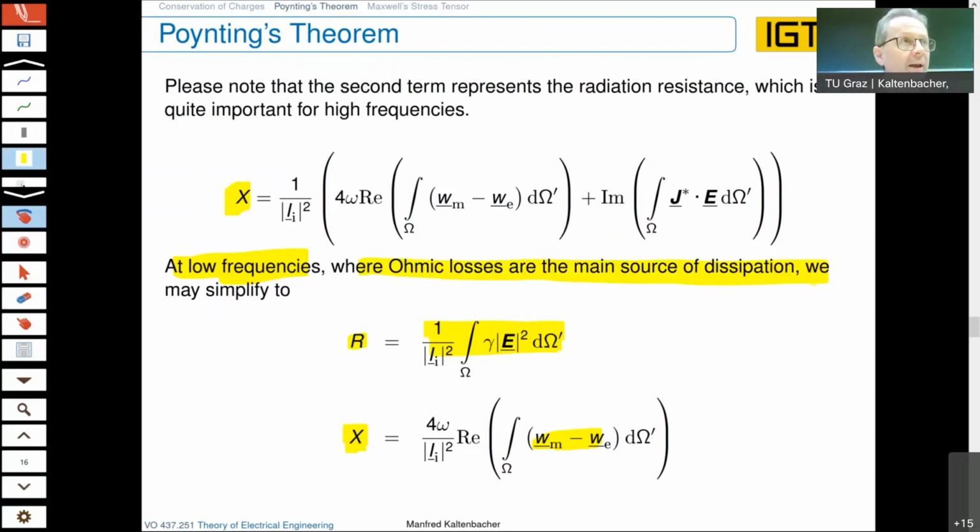These ohmic losses are the main parts as we know. However, if the frequency is increasing, as you know, then clearly you also will have to take part which is induced due to time-varying magnetic fields, which is described by Faraday's law, and inducing any eddy currents, for example, in your structures.